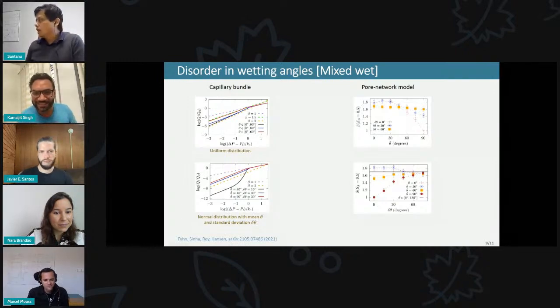Okay, so for most of the results we have, we stay within these two limits, 1.8 or 2. So far we have not received any exponent which is more than 2. Always we see the higher limit is 2, the quadratic dependence, and then it generally decreases to around 1.5, and in some cases close to 1 if it's going towards neutrally wet, something like that.